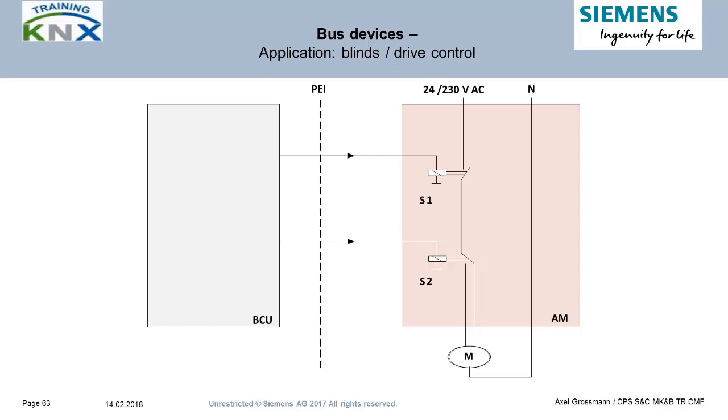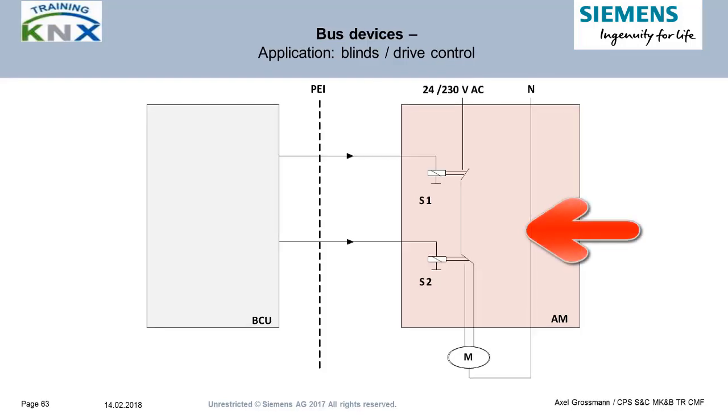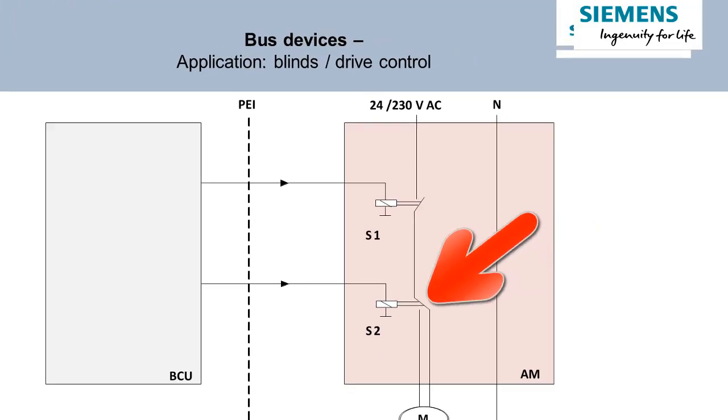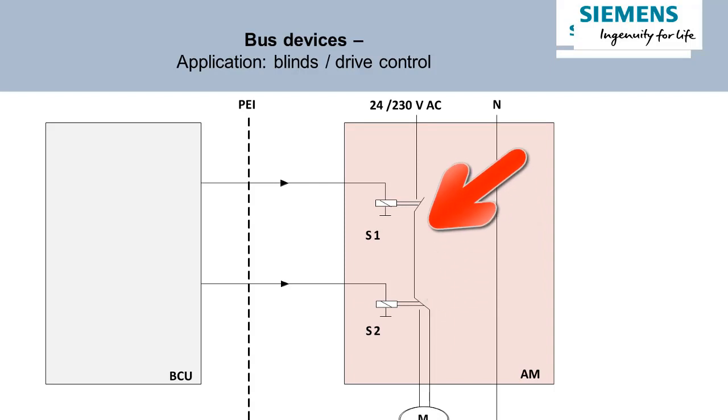For the sun protection actuator, here is also a very simple block circuit diagram. You see that there are two contacts in series. While S2 is the changeover relay, S1 interrupts the power. Motor drives have an inductive phase shift. Single-phase motors also need a phase shift capacitor to control the spinning sense. Both technical details together cause an electric arc over the opening contacts when the motor is stopped.